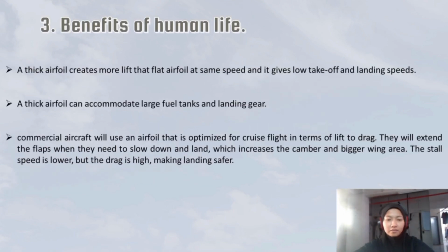A thick airfoil creates more lift than a flat airfoil at the same speed, and it gives a low takeoff and landing speed. A thick airfoil can accommodate large fuel tanks and landing gear. Commercial aircraft will use an airfoil that is optimized for cruise flight in terms of lift and drag.